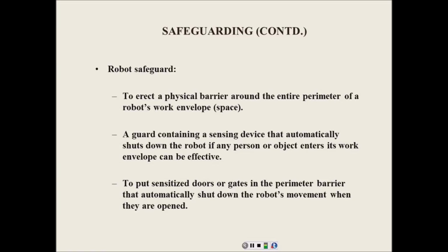But realize if you set your speed on the auto mode to 100%, then the robot is going to run it 100%, right? You understand that? Okay. When you jog it, it's still going to be limited to 250 millimeters per second. The problem that we have is that when you switch it to auto, they don't set a maximum speed of 250 millimeters per second. They drop it down a percentage of that. So when you run your programs, it's real slow.